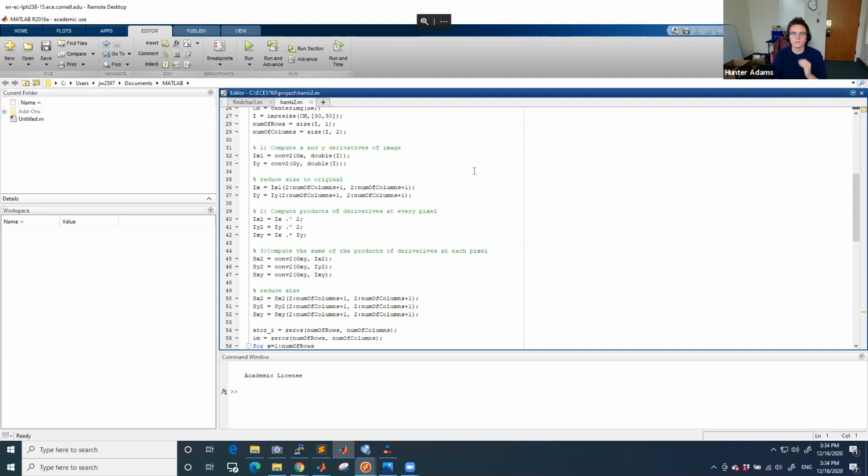Okay. So I want to see if I understand every step of what happens to the image. You send the image into the FPGA. It's grayscale. You send a grayscale image into the FPGA. Yes. It applies a Gaussian filter to that image, and then applies the corner finding algorithm. So did I get that right? The corner finding algorithm requires... we actually combine these two steps.